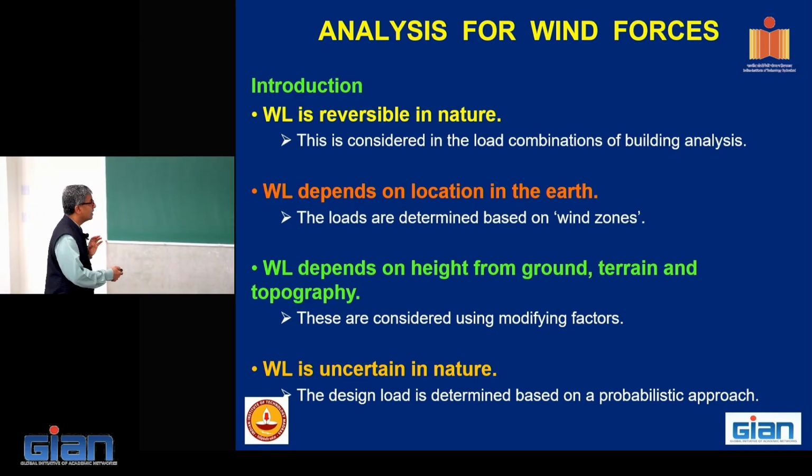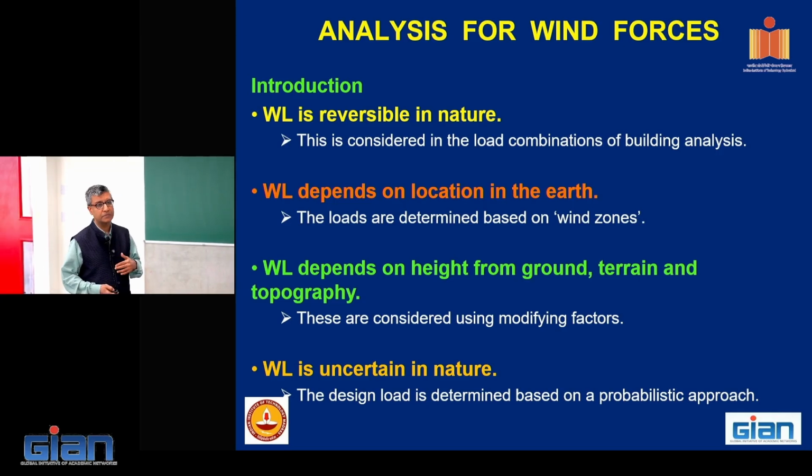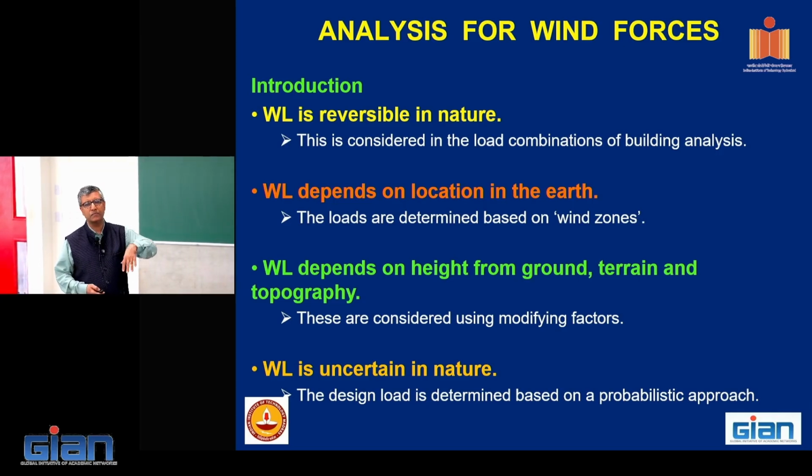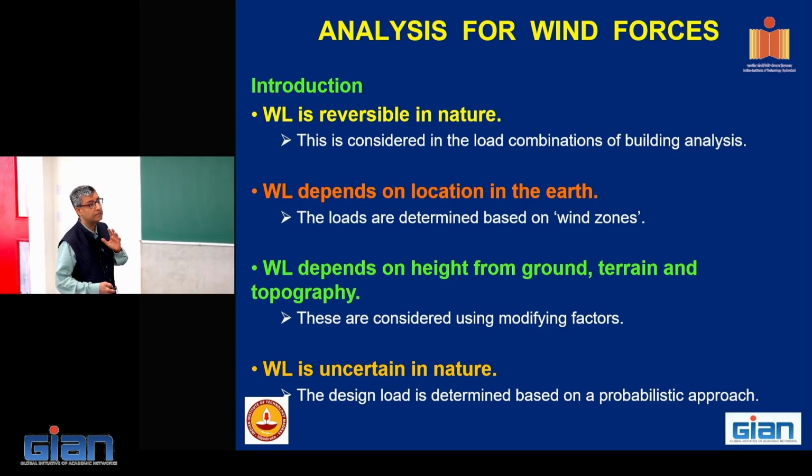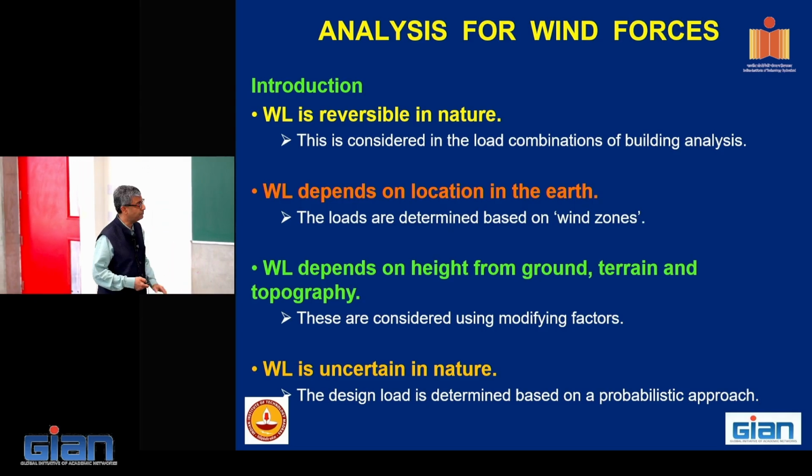It depends on the location on the Earth. Gravity slightly changes if you go up, but that is disregarded in structural design. But wind very much depends on where you are. It also depends on the height above the ground, the terrain conditions, and the topography, and you can understand the complication that is becoming. And a very important thing, it is uncertain in nature, unlike gravity.